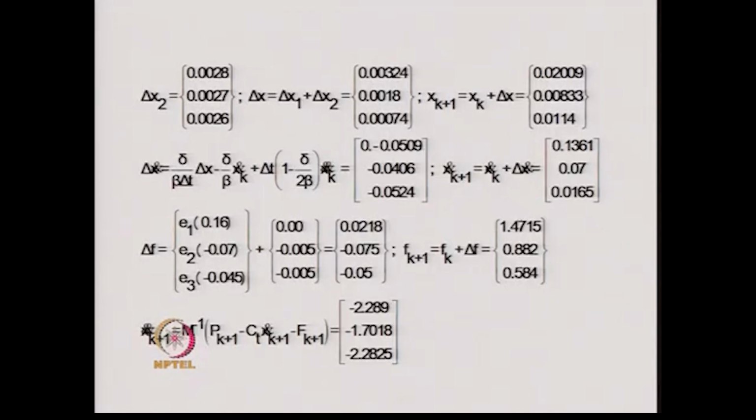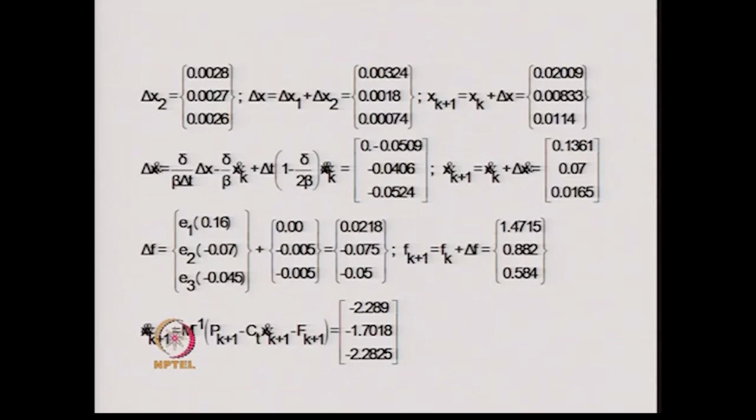Now, the next part is, once we have scaled the displacement to bring the bottom column forces within or equal to the yield shear, then we obtain the next part of the displacement, that is the plastic displacement part. This plastic displacement part delta x2 is calculated using a revised stiffness matrix, and the revised stiffness matrix is given over here. You can see that in place of 200 now it is 100 and this remains equal to minus 100. So, the matrix is changed because of the yielding of the bottom column.